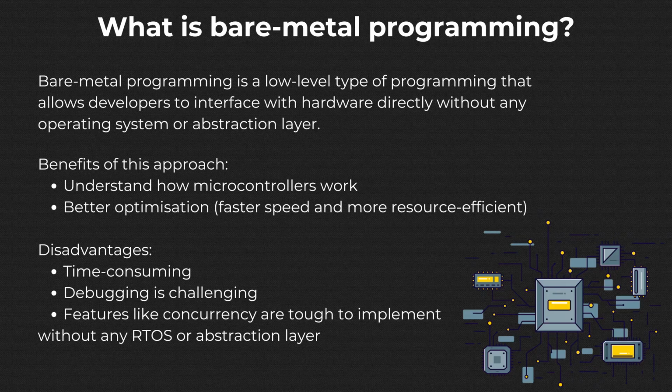Learners can gain an in-depth understanding of how microcontrollers work under the hood without any abstraction to simplify things, such as ST-HAL initialization code seen in the previous setup video. Relying on HAL doesn't offer you much insight into the MCU and ARM architecture. The product of bare metal programming has faster speed and is more resource efficient. This is because the layer of abstraction takes many resources of the system and thus slows things down.